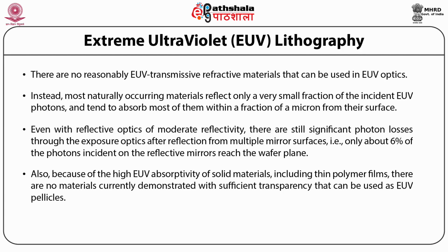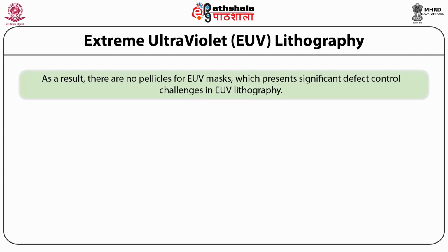Also, because of the high EUV absorptivity of solid materials, including thin polymer films, there are no materials currently demonstrated with sufficient transparency that can be used as EUV pellicles. As a result, there are no pellicles for these masks, which represents significant defect control challenges in the lithography.